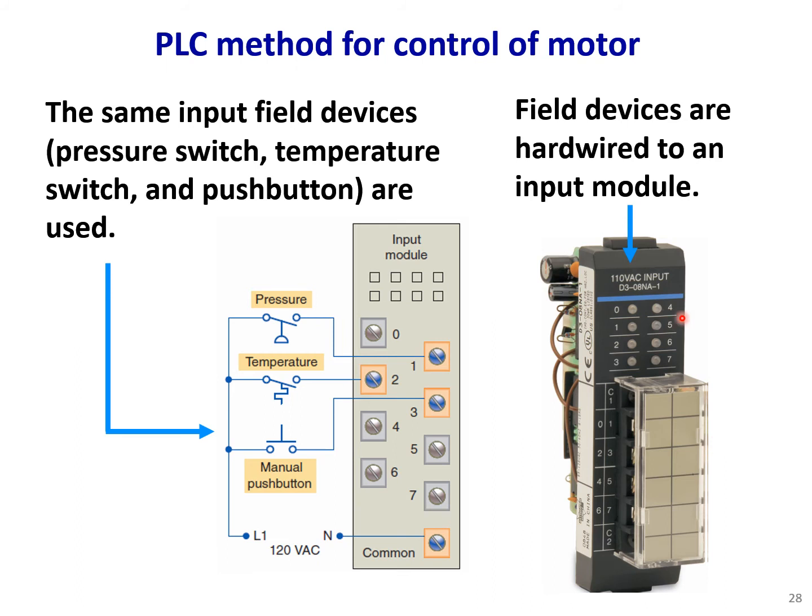Okay, so this is the input module. And in this case, the input module could accept 8 inputs. And the input module type is 120 volt AC also. Okay, this is a digital input module. Okay? We don't have any analog input to the system for this case.